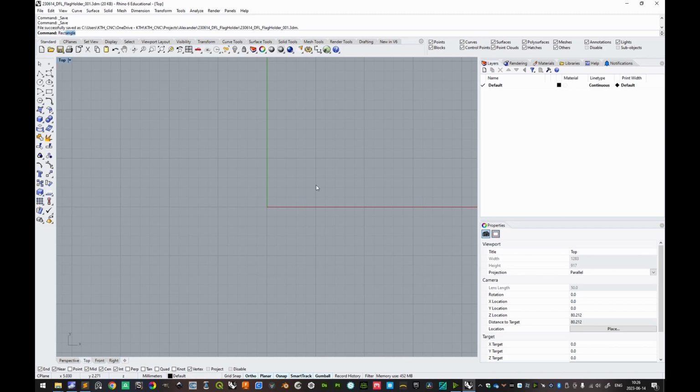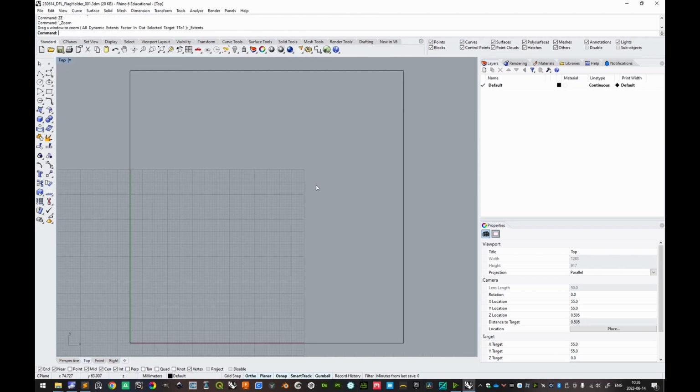And if you type rectangle and then assign the origin as the first corner of the rectangle, the origin is the same as 0. It can be typed as 0, 0, 0, but 0 is fine as well. Enter. And then the other corner or length, in this case it's actually 110 millimeters. And the length or the width is the same as the length, so I'll press enter again. Now, having generated that object, we can type Z and E to zoom to extents, like this.